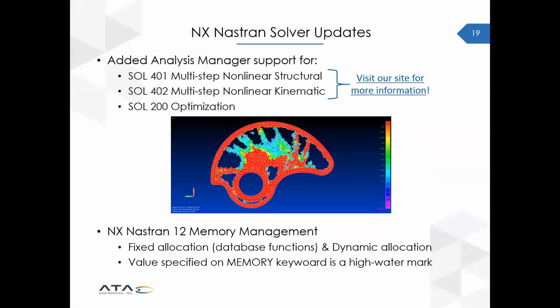I have some tutorial videos and things that I could share with you. These new nonlinear options are very powerful. So you can have multiple subcases. The subcases can be dependent or independent. You can change analysis type between subcases. So maybe you want to start with a preload and then you want to run modes on that. You can do that with consecutive subcases. You can change contact between subcases. So there's a lot of options there.